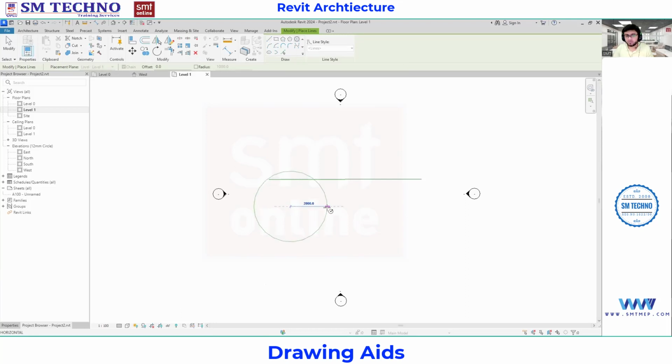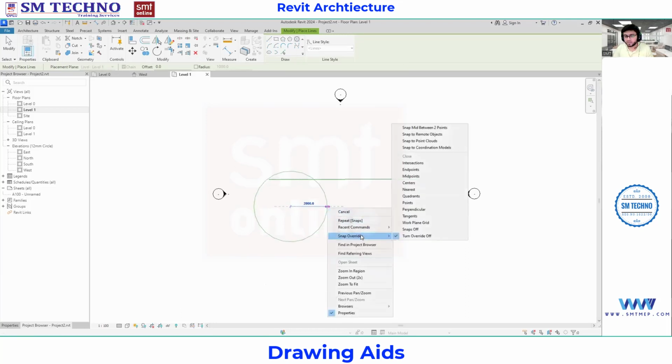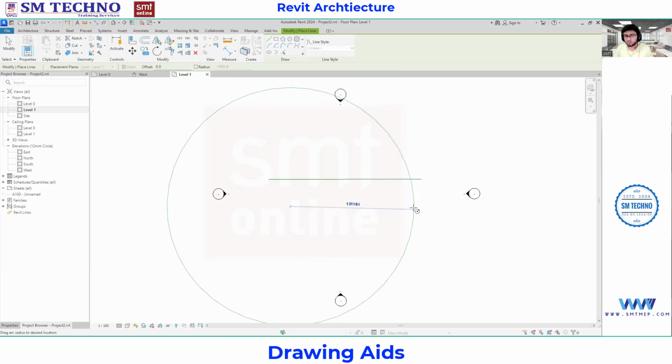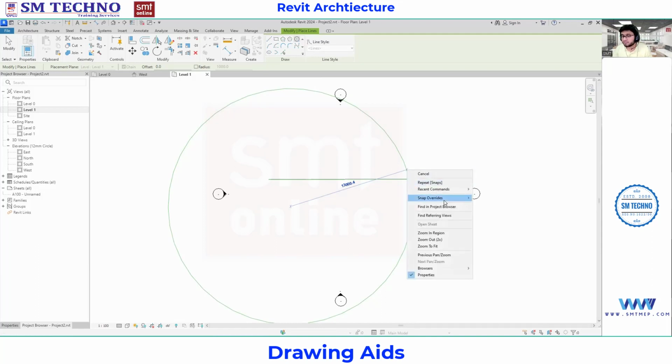When you draw the circle, if you want any kind of tangent point, for example, select the tangent point. It will give the tangent point directly. These things are available when you go with the snap, and this is for one click only. It won't be enabled for a long time; we don't have the enable or disable option over here. Temporary snaps are the options we find over here.